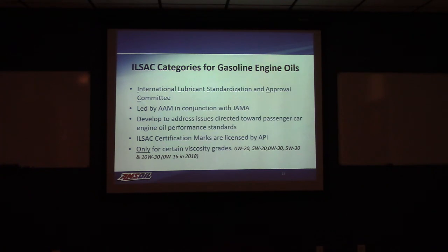They only deal with gasoline engines, not diesel. So never look for an ILSAC specification on a diesel oil, because that's beyond their scope. They also only deal with lighter viscosity oils, your 0W20s, 5W30s. You'll never see a 10W40 with an ILSAC spec, or a 20W50.